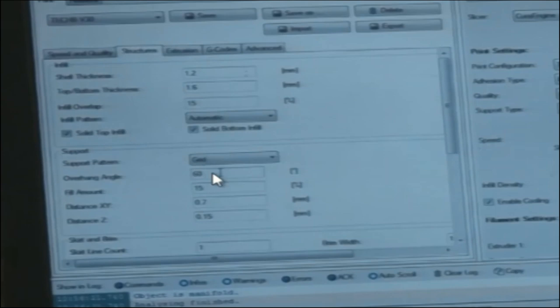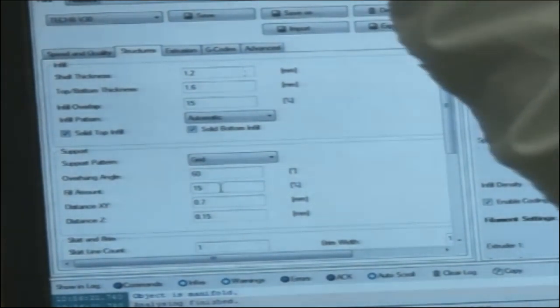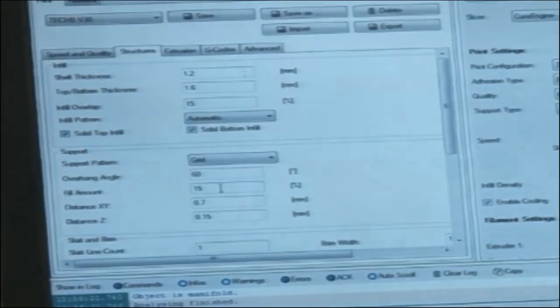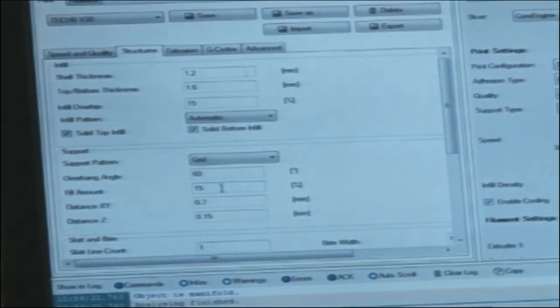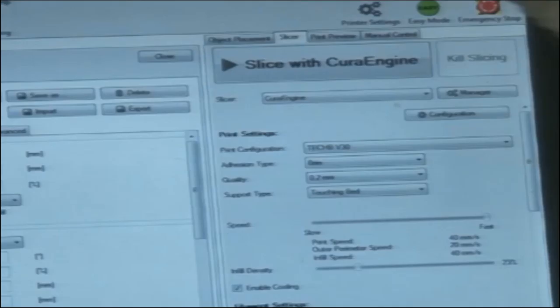The overhang angle is 60 degrees here, for this machinery. If we are going to deposit, or print, or manufacture any job, if it is solid, there is no issue at all. If it is a conical shape, an angle up to 60 degrees is fine.